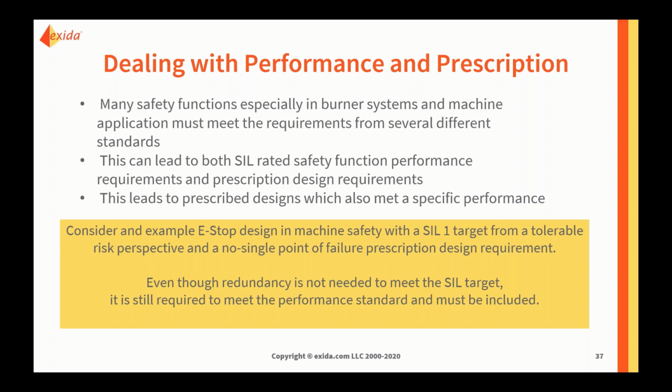And if you have a performance requirement and a prescription requirement, you must meet both of those requirements in parallel to ensure that you have met the overall requirements for operation of your system. Now, this comes up again and again with e-stops. For instance, if you have an e-stop requirement of SIL 1 from a tolerable risk perspective, you can easily identify some designs that have single points of failure in them and still achieve SIL 1.